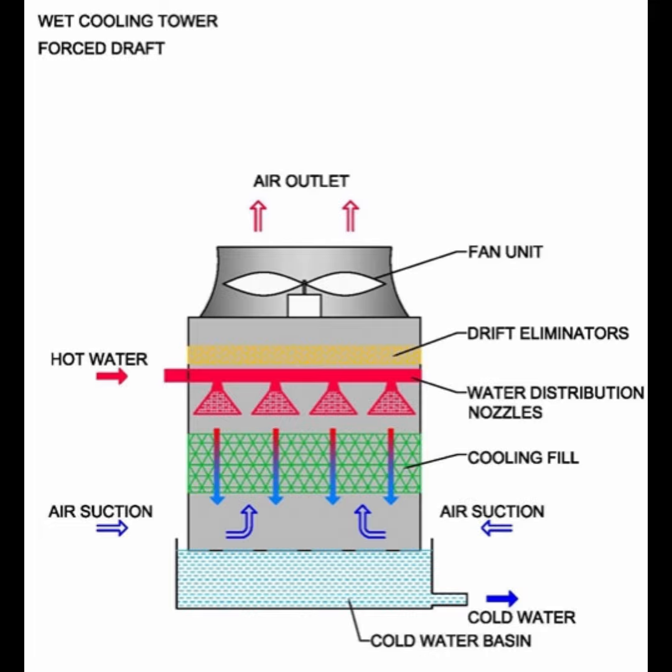Water distribution nozzles. These nozzles spray the hot water evenly over the cooling fill. Cooling fill. This is a material, often made of PVC or wood, with a large surface area. It maximizes contact between the water and the air, promoting efficient heat transfer through evaporation.